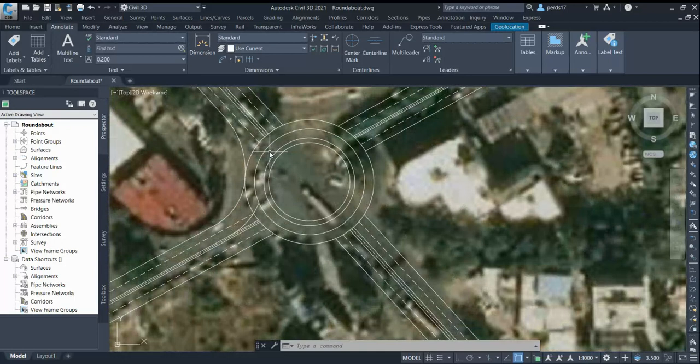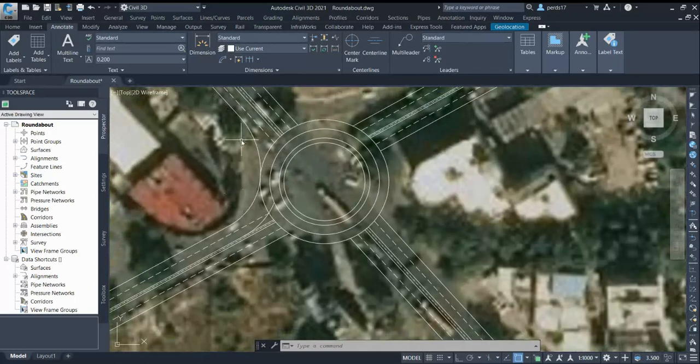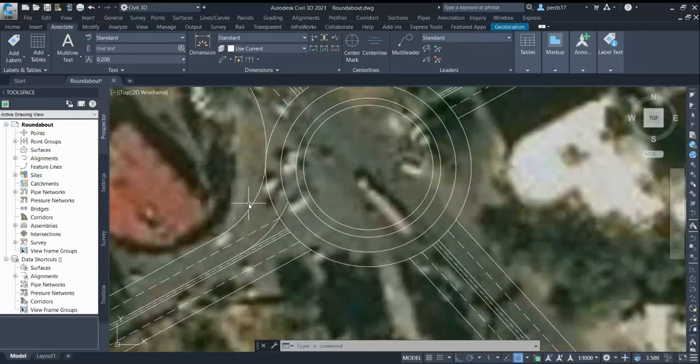The third parameter we went through is the entry radius. Like I said, the entry radius and the adjacent exit radius should not overlap. So that's how you decide it. That's the first thing. Second, you need to look at your site constraints, and then based on trial and error, we decided on one entry radius, between the minimum 10 meters and maximum 100 meters. So I went for 25 for this example, based on my experience.